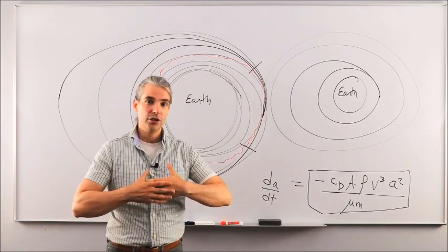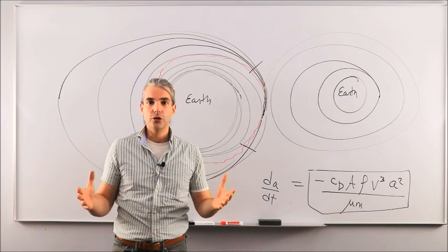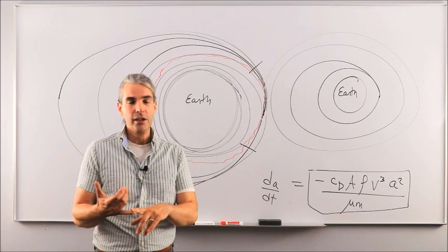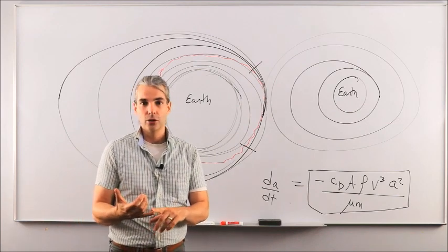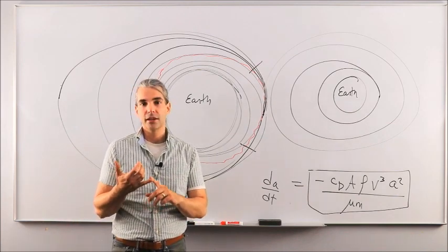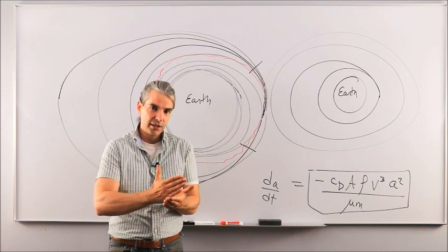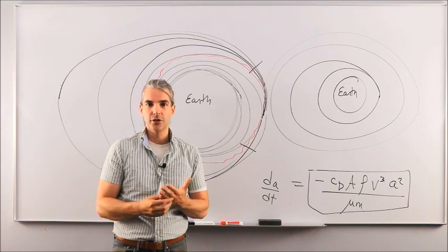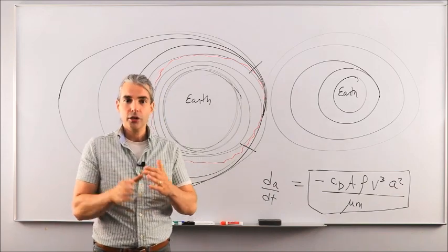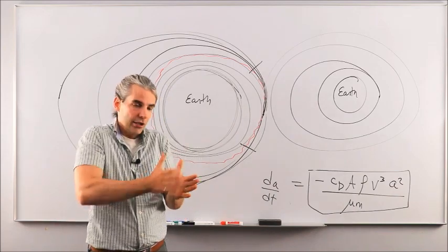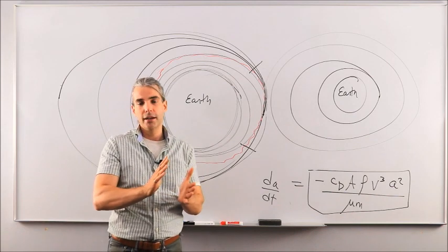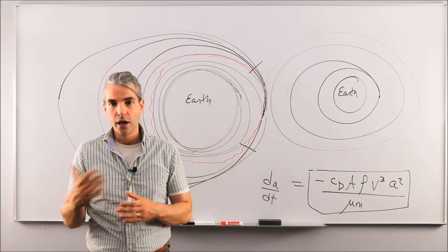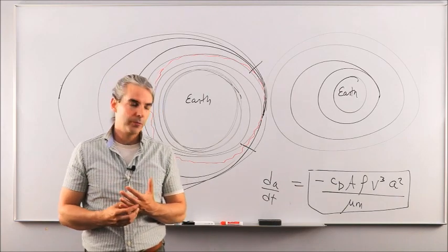And we saw that these two could lead to two beneficial effects: Sun-synchronous orbits, for which the LTAN, the local time of ascending node, remains constant because the orbit shifts at the same rate that the Earth rotates about the Sun, and also a critically inclined orbit, to ensure that the perigee does not shift inside the orbital plane by selecting the inclination properly to null out the average rate of change in argument of perigee.